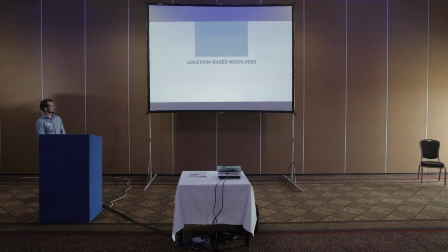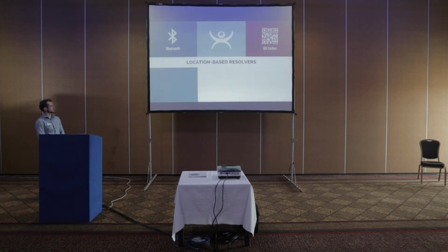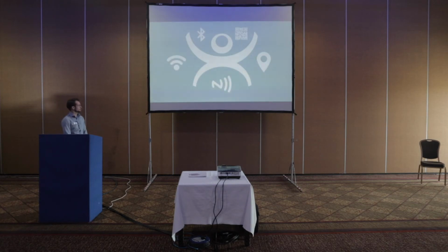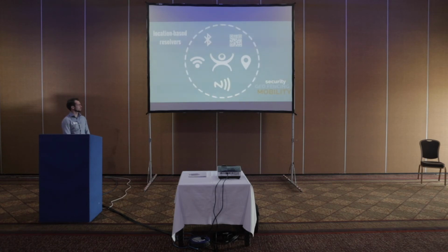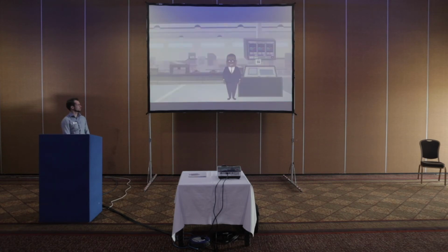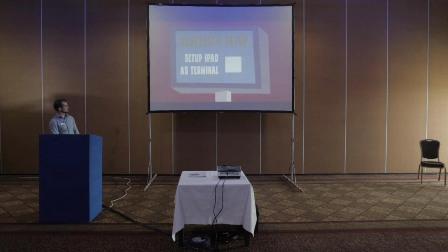Location-based resolvers with Thin Manager can be set up using Bluetooth, QR codes, NFC, Wi-Fi, or GPS, or any combination desired to create geofences for total security when integrating mobility into your production environment. Using a small Bluetooth beacon at the production line, Phil creates a fence around the line in which the iPad is allowed to function. He can then set the iPad up in Thin Manager as a terminal with the location of the Bluetooth area he has created.